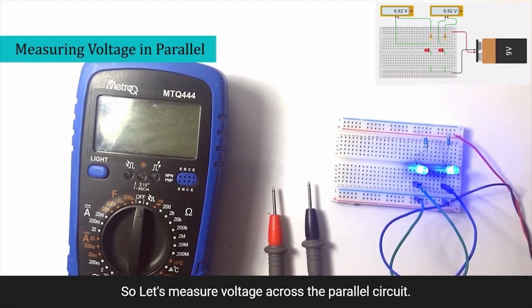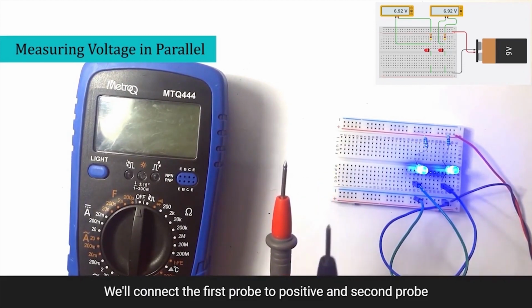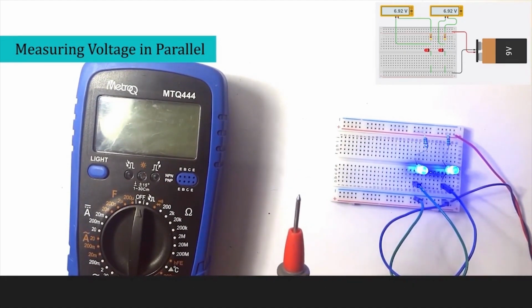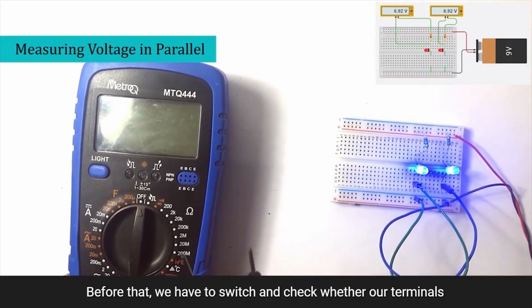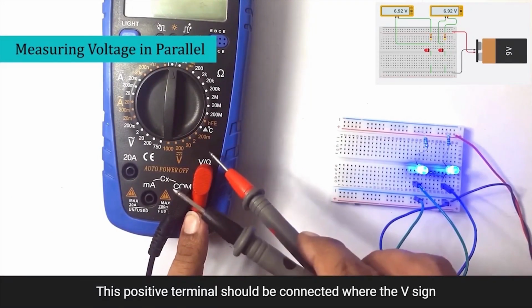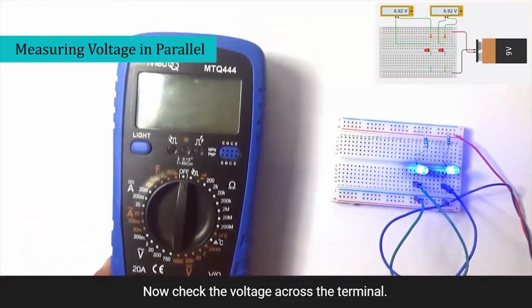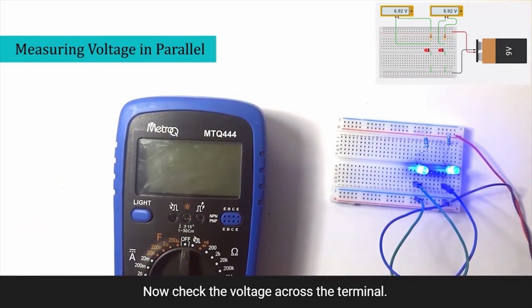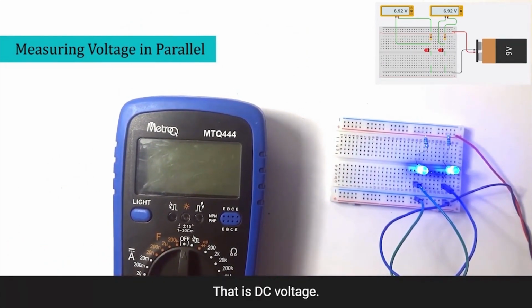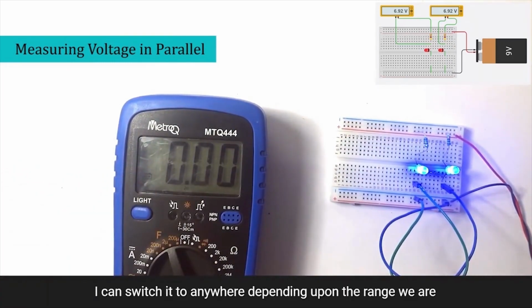So let's measure voltage across the parallel circuit. We do have two probes here. We'll connect the first probe to the positive and the second probe to the negative of the circuit. Before that, we have to check whether our terminals are connected properly. The positive terminal should be connected where the V sign is written, and the negative should be at the common. Now, to check the voltage, I have to switch the knob to V, that is DC voltage. I can switch it to anywhere depending upon the range we are trying to take.